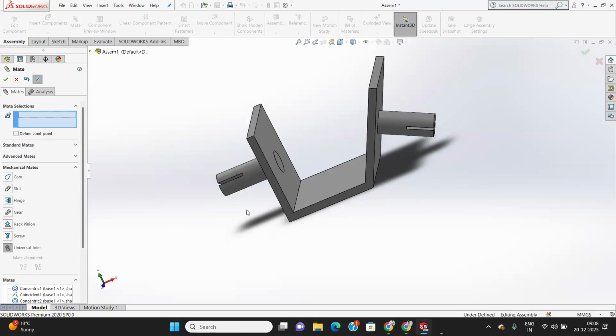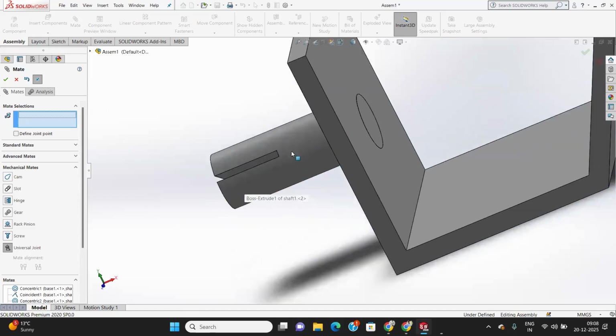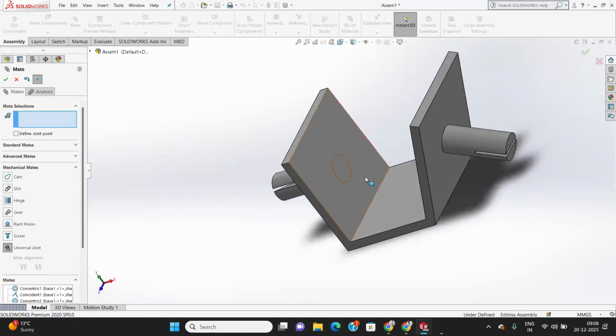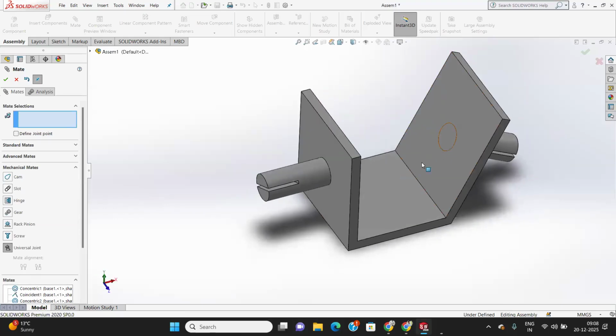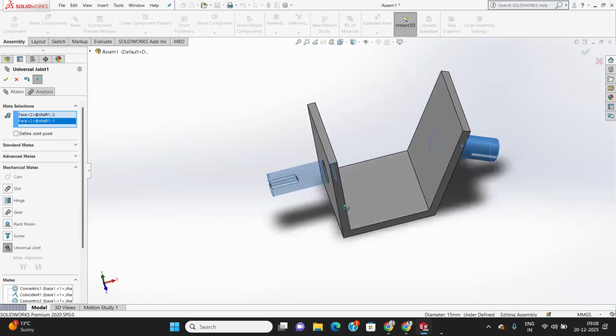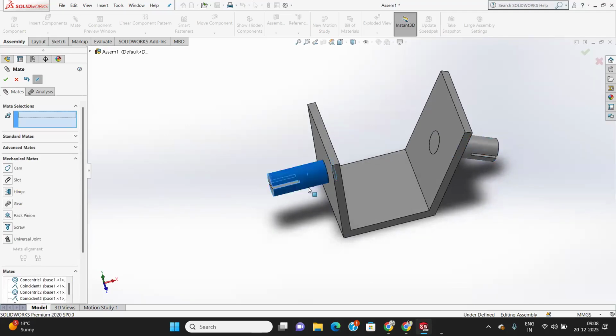In this case, you select the object where you selected. You can select the edge of this object also. If you select the face, then you select the same face of this object. If you select this body, then you select the same body for this object also. After you click on OK, if you rotate one, then the other one is always rotated.